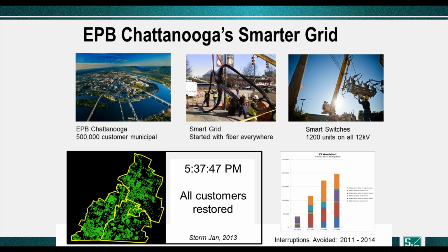And the picture there is looking at a real event, 2013, where a tree fell across a right-of-way and actually knocked out power to 12,000 homes. The way the system reacted was, again, a Waze approach, talking to each other. Within 42 seconds, 98% of those people were re-energized because it had distribution intelligence in there. And the following 2% were re-energized about 3 minutes later once control got involved. But that starts to show you some of the power in how you address it. So next slide, please.